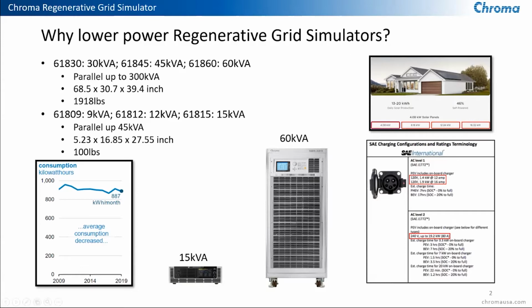I've included this picture here, the top right-hand corner. We can see one company's different models it has to offer. There is a 4 kilowatt option along with an 8 kilowatt, 12 kilowatt, and 16 kilowatt options. There are also standards such as the SAE J1772 standard, which is also known as the J-plug. It is the North American standard for electrical connectors for electrical vehicles.